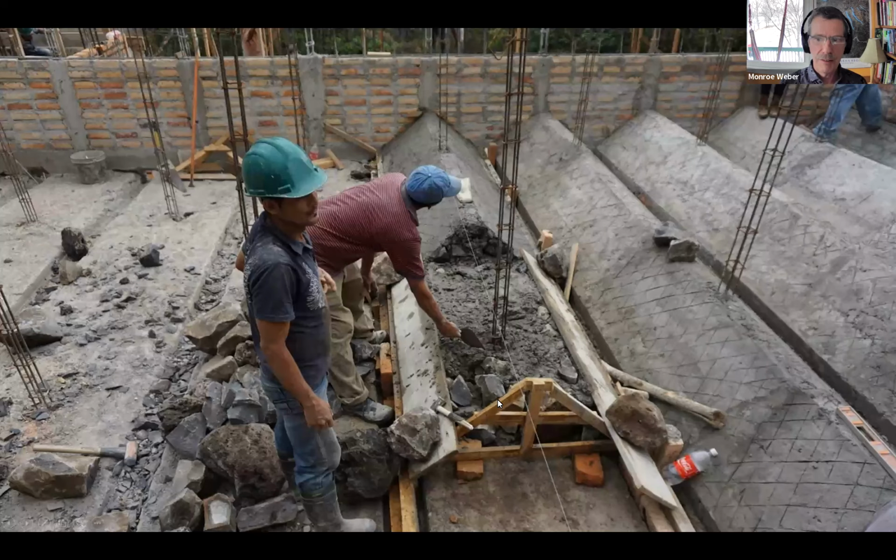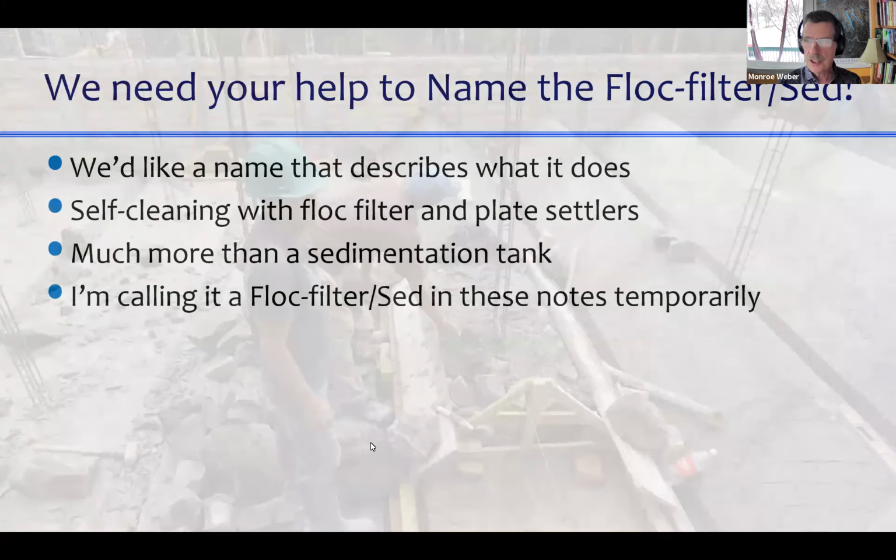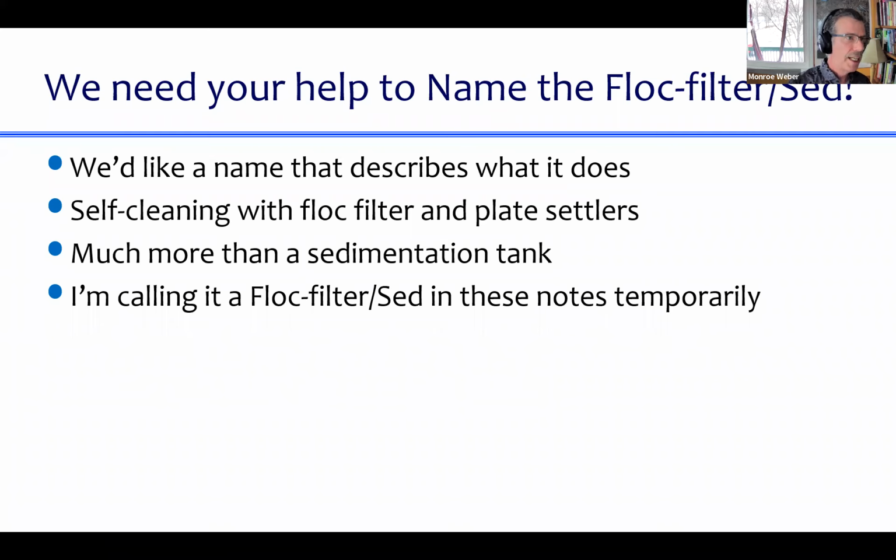Here are some views of workers fabricating these systems, building these systems in Honduras. So they're making the sloped sides and bottom of the sedimentation tank. Wait, yeah, so I'm asking for your help. We'd like a name for what this system is. It's self-cleaning, with a floc filter and plate settlers. It's a whole lot more than just a conventional sedimentation tank. And I'm calling it a floc filter sed in these notes, but we're looking for a better name for this.